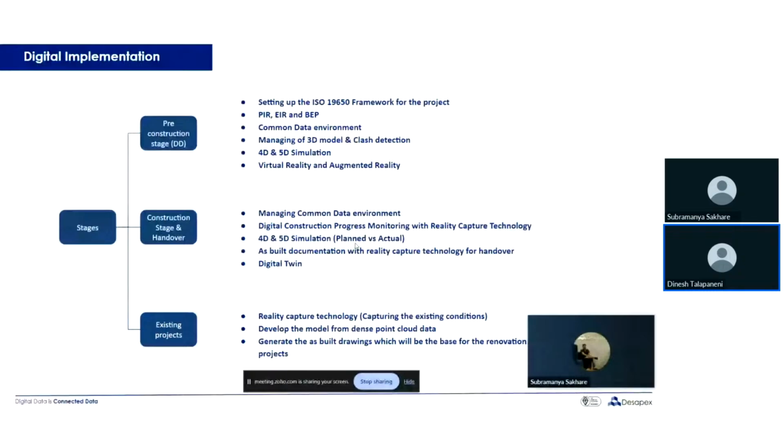So that's about 4D. And there's always this question: when is the right time to start 4D? People say, okay, we'll just do one video for the sake of doing it. But we need to have certain BIM goals, like exactly what needs to be done. So when is the right time to start the 4D? I would say design development is the right time to start the 4D.